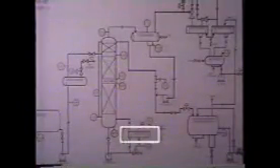Now let's look at the board again and see how the emergency shutdown procedure affects the system. In this procedure, the feed of mixture to the column and the takeoff of products have been stopped. In addition, the steam used to heat the reboiler has been shut off, and the vacuum system has been shut down. Although the column is almost completely shut down, it can still be restarted more easily than it could if a long-term shutdown had been performed, because there is mixture in the column which is being recirculated.